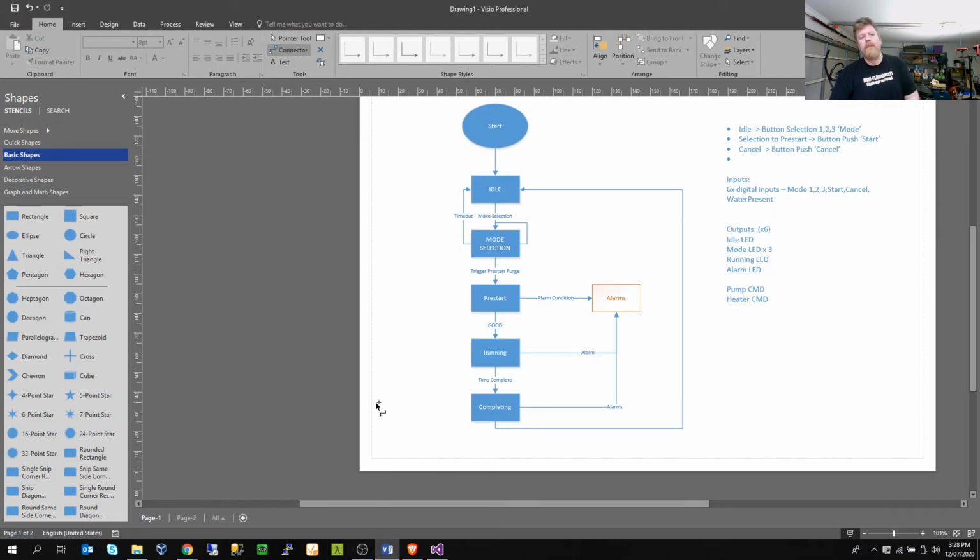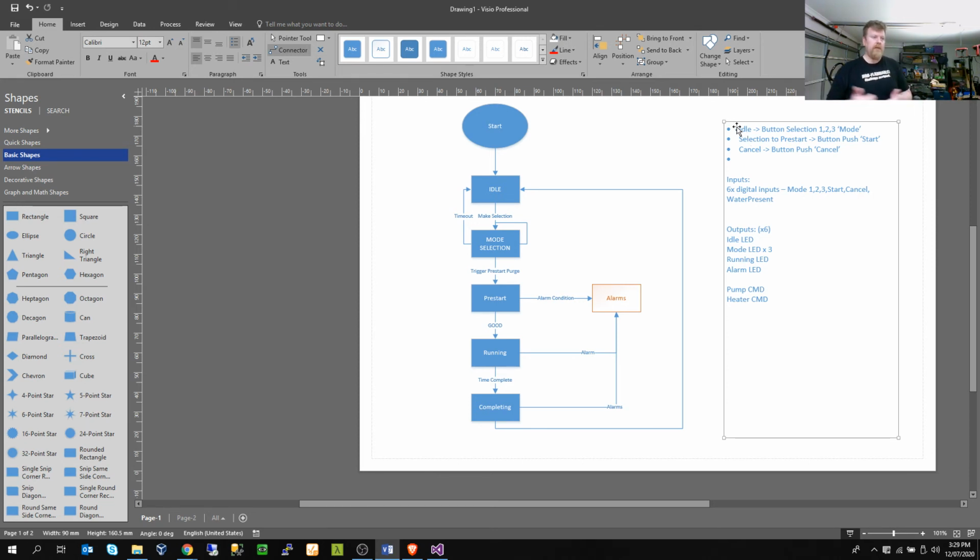So moving from that idea back to our finite state machine. For our example of a dishwasher, we could look at things like the number of buttons we've got, inputs and outputs and things like that. For small processes like this, it's quite easy to think about the inputs and outputs. When you get to very large scale things, understanding your requirement specification is going to be more important than understanding your I/O. It's a common trap to go down the path of saying, if I map out all my I/O, it's going to give me enough information to understand what I need to do. I just read it in, do some stuff, map some things out. How hard can it be? Probably a little harder than that in reality.